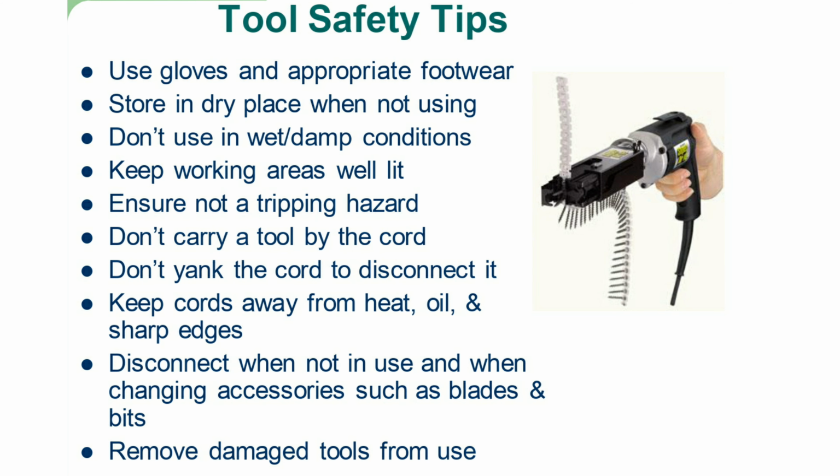Tool safety tips: use gloves and appropriate footwear, store in a dry place when not using, don't use in wet or damp conditions, keep working areas well lit, ensure it is not a tripping hazard, don't carry a tool by the cord, don't yank the cord to disconnect it, keep cords away from heat, oil, and sharp edges, disconnect when not in use and when changing accessories such as blades and bits, and remove damaged tools from use.